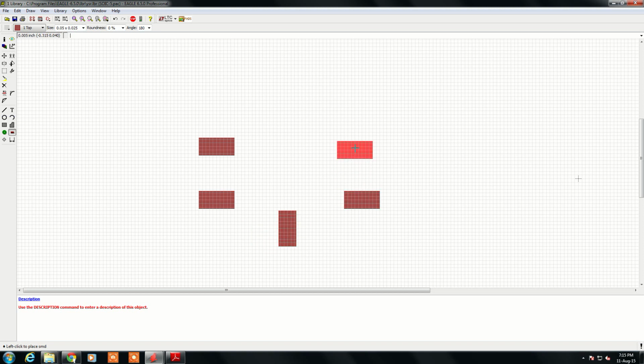You should be very careful while choosing the pads, because when you take the printout of this and place the component, it should match 100%. There should not be any difference in terms of package and placement of the component.